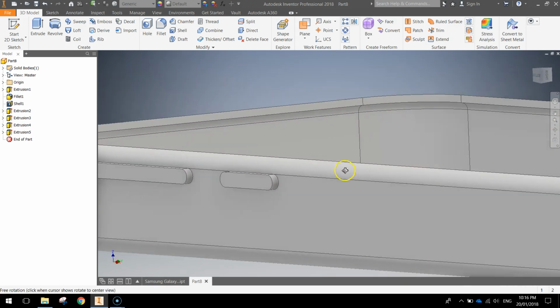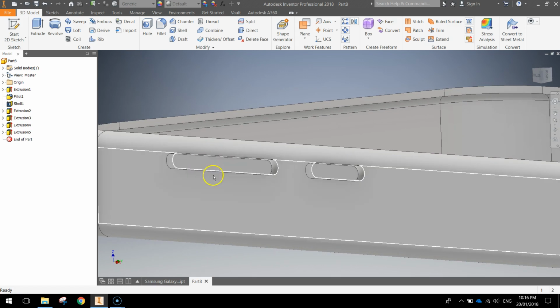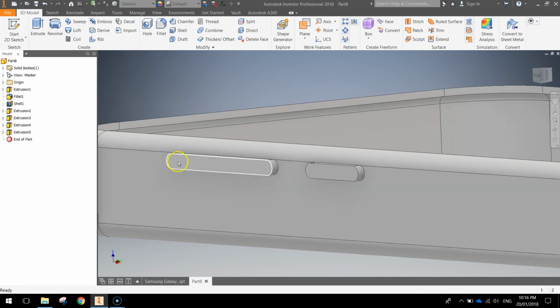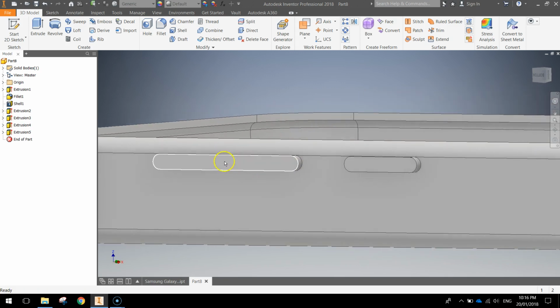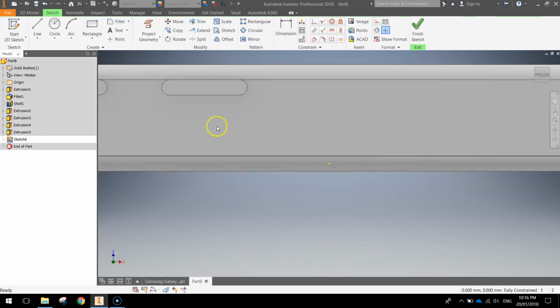Now one thing we need to do is just touch up this volume button a bit. Okay, if we press the top end, that turns the sound up. If we touch this bottom end, it turns the sound down. What we want to do is just put a little barrier in the middle here so you can distinguish between volume up and volume down. I'm going to start a 2D sketch on the volume button itself.